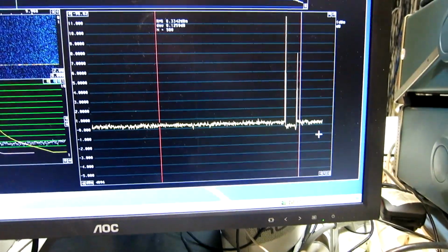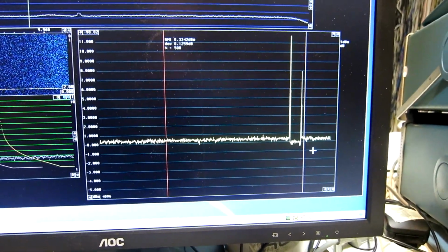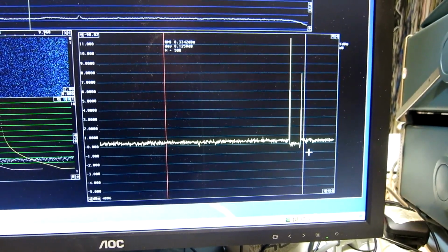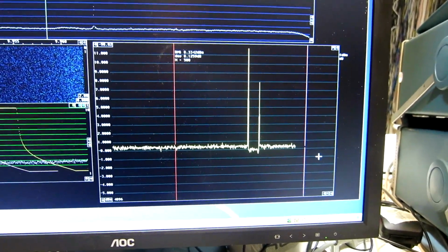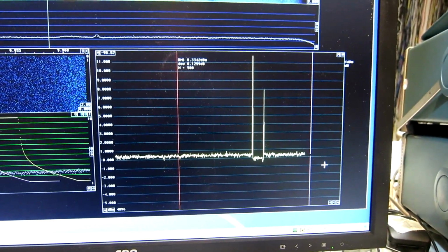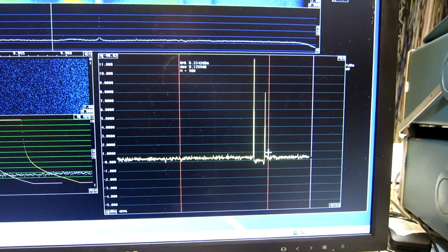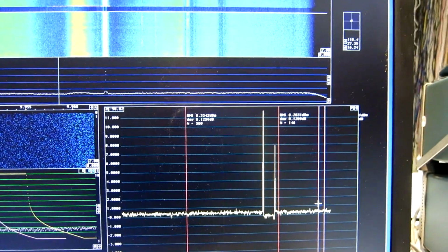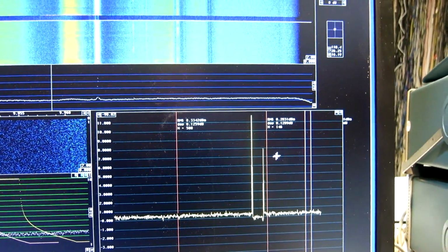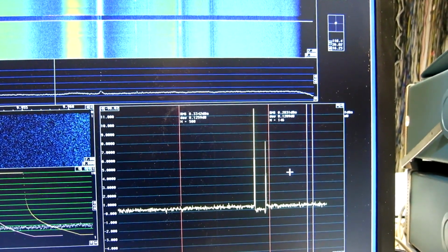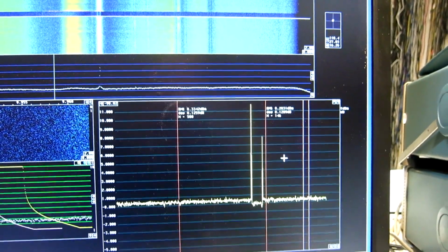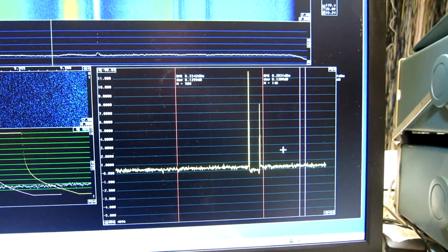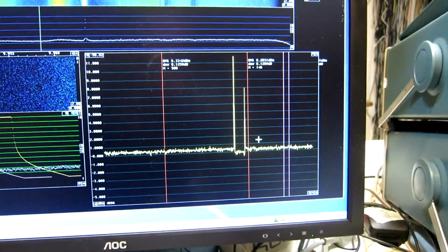So it means this capacitor does not add any noise, or at least very little. So if I read this out from the straight-through wire, it says 0.28. So this difference of 0.05 dB may be statistical uncertainties.